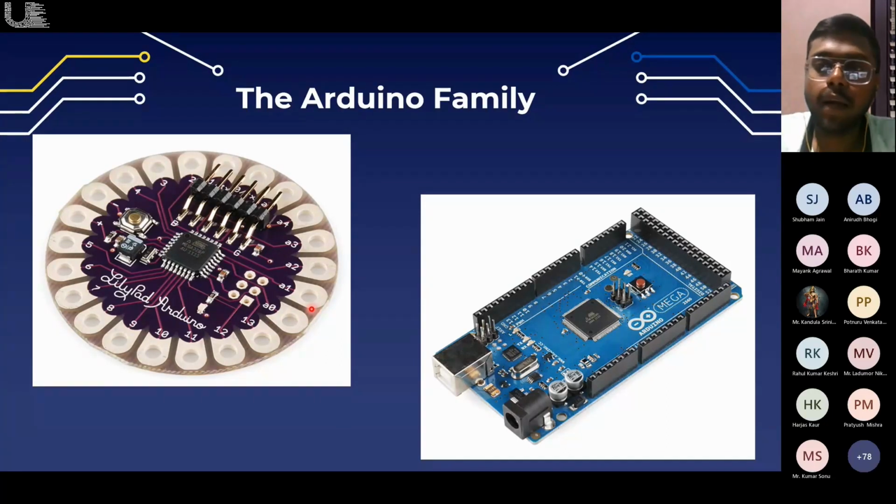Each LilyPad was creatively designed with large connecting pads and a flat back to allow them to be sewn into clothing with conductive thread. The LilyPad also has its own family of input, output, power, and sensor boards that are built specifically for e-textiles. And this board is even washable. You see here the number of input output pins differs, but the overall structure remains the same. There is a reset button, there is an input power supply, there is a microcontroller, there are input and output pins.